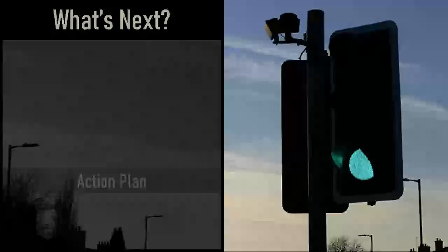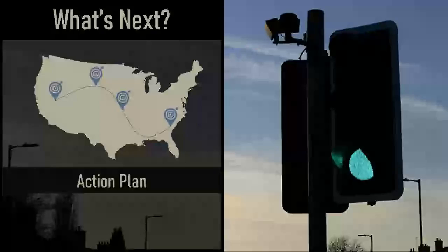So what's next is really creating an action plan. If you have roadway networks that you're responsible for and haven't done the horizontal curve assessments, I encourage you to create a plan of how you want to accomplish it. You can do a lot of it yourself if you want, particularly driving. I break it up into essentially 4 tasks: route planning, data collection, processing, and quality control. If you're comfortable doing all 4 of those, you can do all 4 of those. If you want help in any one of those, we're more than happy to help you.